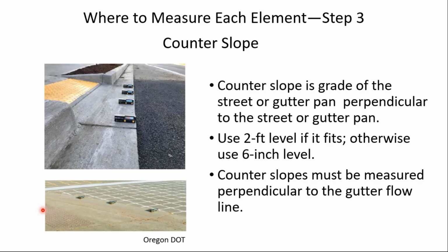Thanks, Ron. There was a comment from Shane. He said it might be worth noting that cross slope and running slope for ODOT is not 8.33 and 2.1. It is 7.69 and 1.56. So I reached out to our Office of Roadway Engineering a few minutes ago, and they wrote back.